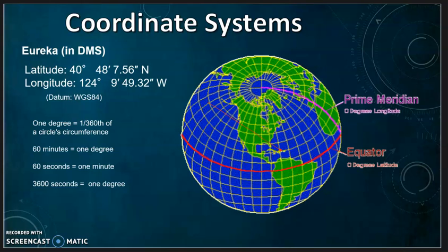Latitude and longitude are measured by using a sexagesimal or base 60 system. Similar to units of time, one divides degrees of latitude and longitude into fractions of 60, so each degree consists of 60 minutes, and each minute consists of 60 seconds. The horizontal datum, the prime meridian, and the angular units of lat and long together form a geographic coordinate system.